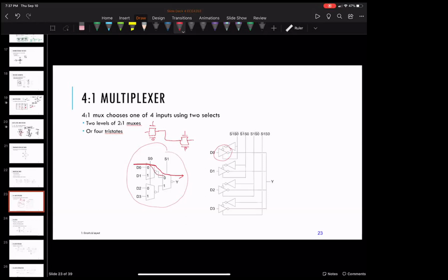Each one of these layers has a resistance, so your signal quality suffers. You still get a full voltage value, but the resistance increases because each layer has a resistance. If you're driving a capacitance, it could slow outputs down, so I have to be a little bit careful about that.